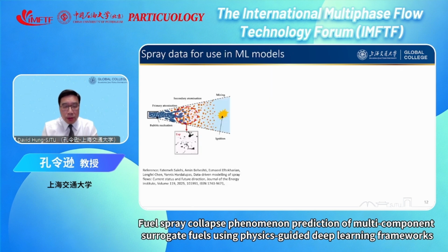Now, let's come back to the spray. I'm, again, very grateful for Dr. Pinotello to tell you about all the spray. And it's fascinating, in my opinion, because the liquid becomes so dispersed. Different liquids show different behavior. And this is just an example of the liquid coming from a nozzle. You can see a lot of things happening. You have bubble nucleation, you have primary breakup, you have secondary breakup. And you know what? If you want it to ignite in case of fuel, then it does. So the mixing between the liquid fuel and the air creates a lot of challenges.